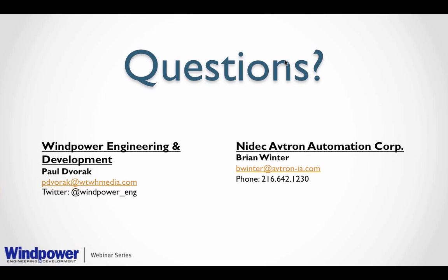How can we maybe resist encoders for humidity? I think you must protect encoders from humidity, salt, in applications close to the sea. Very good question. The truth is, for an optical encoder, there really isn't a good way to protect them, which is why Avtron's not very. We try to avoid selling our optical encoders for wind turbine applications.